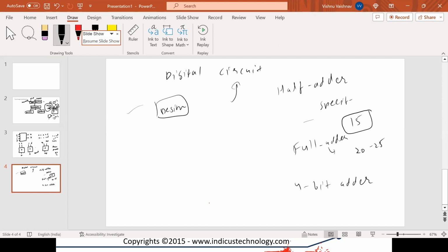No. By just following such a process, or by just writing the code in Verilog, VHDL or SystemVerilog, can you come and say your code would work perfectly fine? No. What do you need to do now? You need to test your circuit. If it's a half adder circuit, you need to test it. You need to make sure you are verifying. Without doing that verification, you won't come to know whether it works perfectly or not.